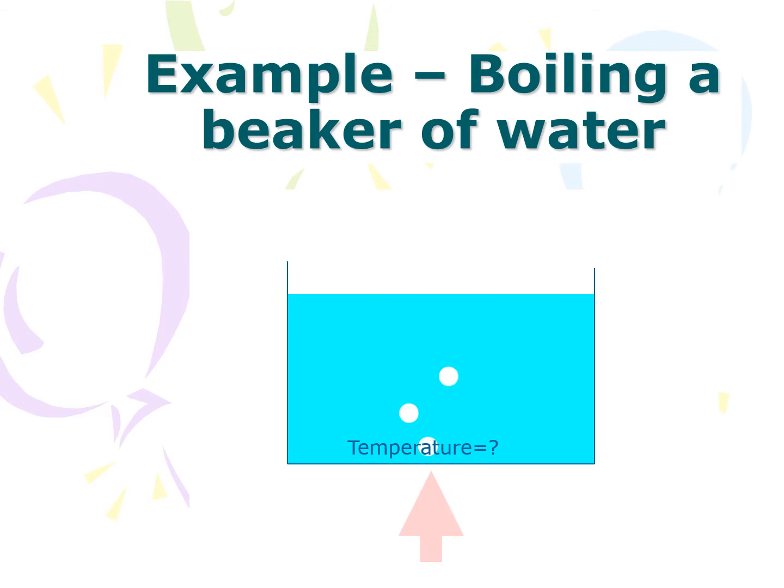As the vapor or steam bubbles move up due to buoyancy, water streams in from the side to replace the volume. Hence you have convection heat transfer. As you saw before, this is heat transfer from a surface to a moving fluid. As you know, boiling can be quite vigorous, hence you can expect a high heat transfer coefficient.